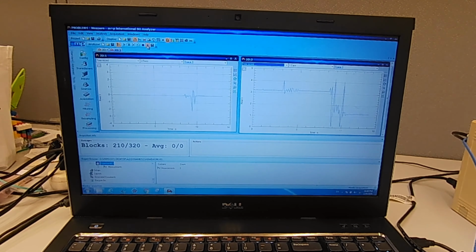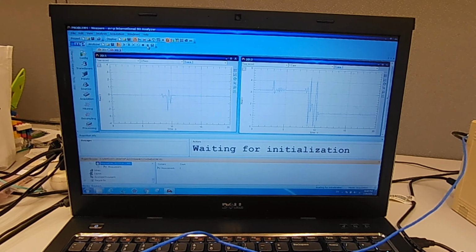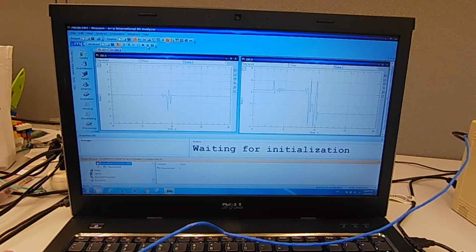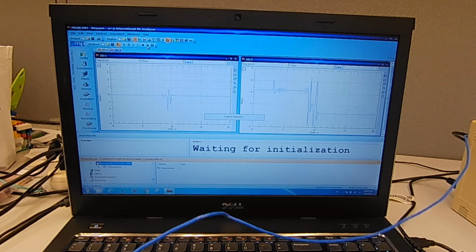Now what's clearly visible is that with the piezoelectric, we're not able to see that shift, that translation in the signal, whereas with the capacitive, we're definitely able to see it. And so this tells us, yes, the capacitive accelerometer is indeed able to measure the gravitational pull.